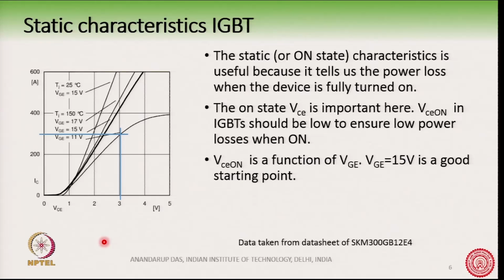So, therefore, this tells us that VGE should be sufficiently high. Okay. Usually 15 volt VGE is a good starting point, okay, for these devices. That is also recommended in many of the application notes and data sheets.